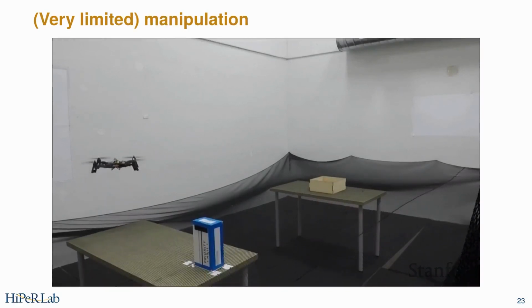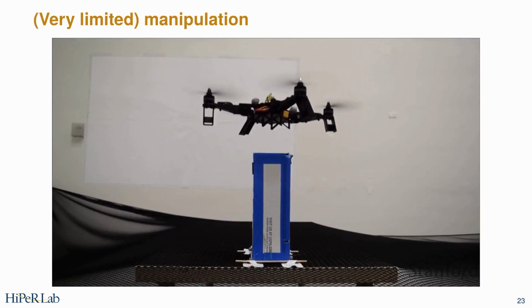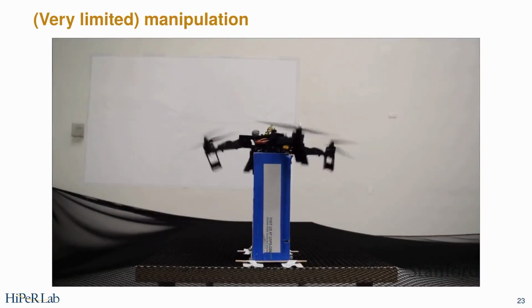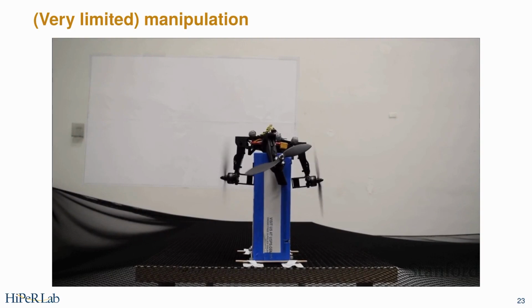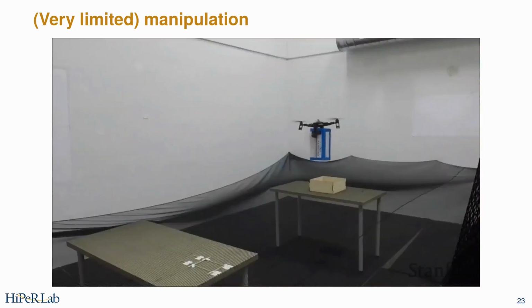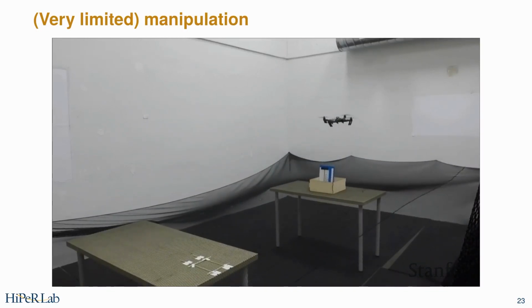You can also do some sort of perching with this as well. So if you land on a wire, and I sadly don't have a video, the 4 arms fall down, and that moves the center of mass below the contact point, so you have a very natural perching behavior. It does come at some slight cost, so there is some control logic where you want to be careful about thrust limits so you don't accidentally fold the system, but that effectively just moves your minimum thrust up slightly.